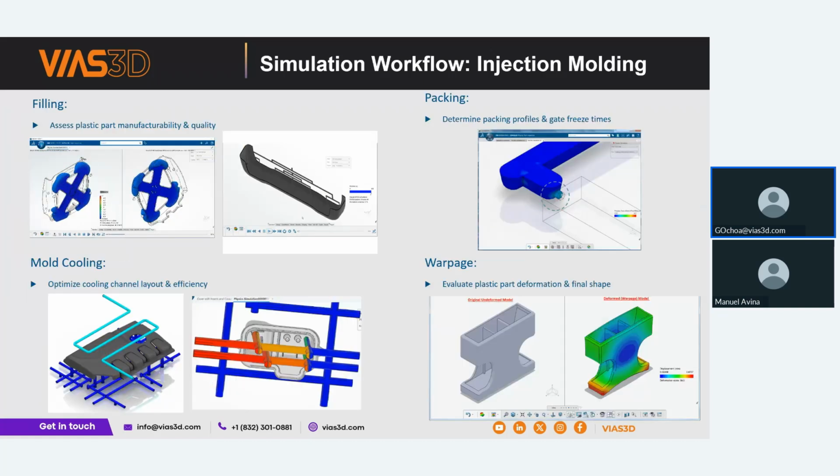Going deep on the injection molding simulation workflow, what's available here is users can simulate the filling phase of the process in responses such as plastic pressure, temperature change, weld line predictions, air traps, all those kind of things related to the filling stage of the injection molding process. On the other side, and this is going to be very relevant for the upcoming workflows, it's going to be the packing phase, where we are simulating the packing profile or the holding stage of the injection molding process.